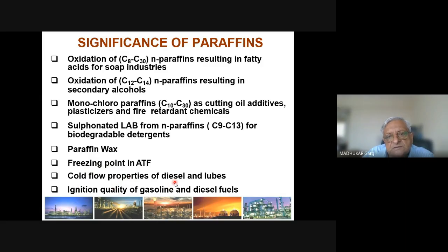It also affects the freezing of diesel in the vehicles in our country. During winter, we have diesel with what we call a pour point or freezing point of plus 6 degrees Celsius, and in the summer plus 12. But if you have a very cold day, the diesel can freeze in the tank. So you may have seen some drivers using logwood to create fire and then melt the diesel in the diesel tank on board a truck.